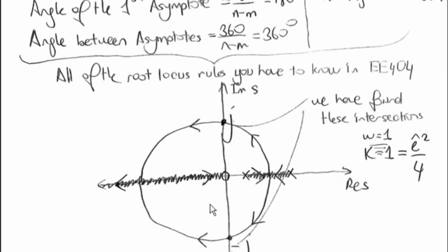So now if I look at the root locus, I would obtain a figure like this. So I have real of S and imaginary of S. I have the open loop poles here. We know that the root locus goes from open loop poles to open loop zeros or to the asymptotes. So here I have two open loop poles here and here, and one open loop zero at the origin, and the asymptote is here looking towards this side. So it has a 180-degree angle, so it is on this line. So one of the closed loop poles is going to go towards negative infinity on this line here.